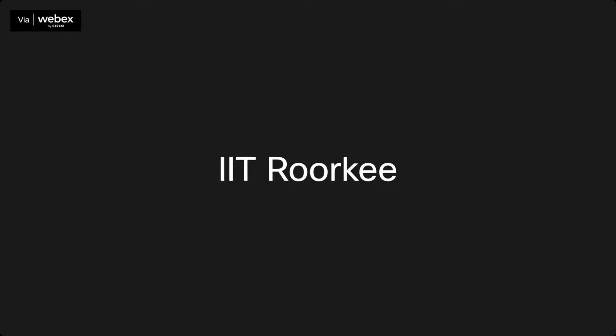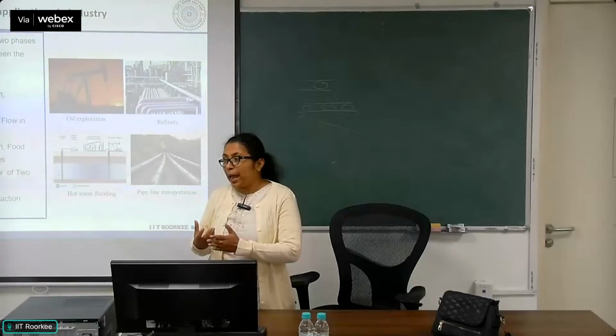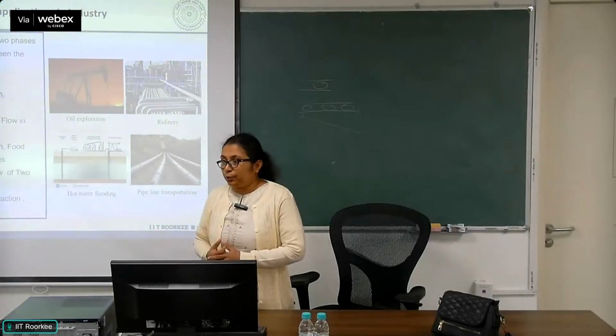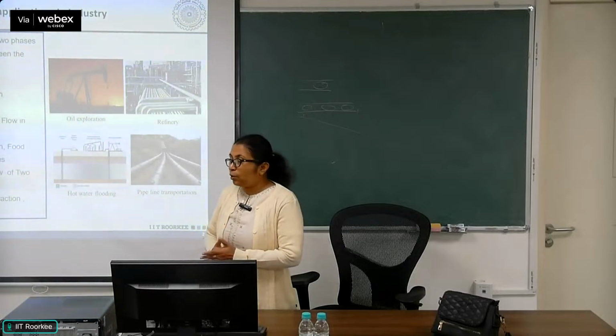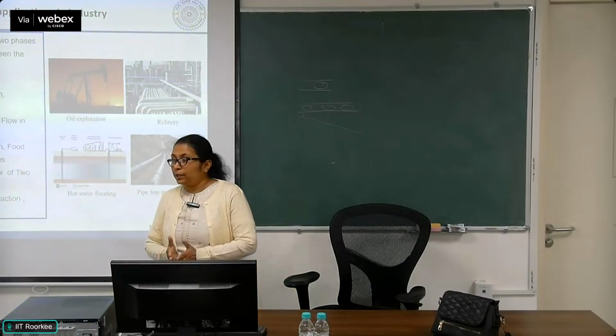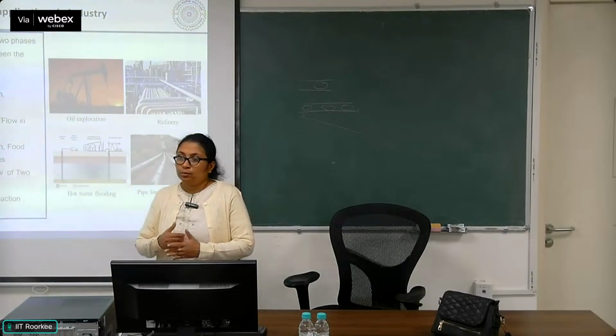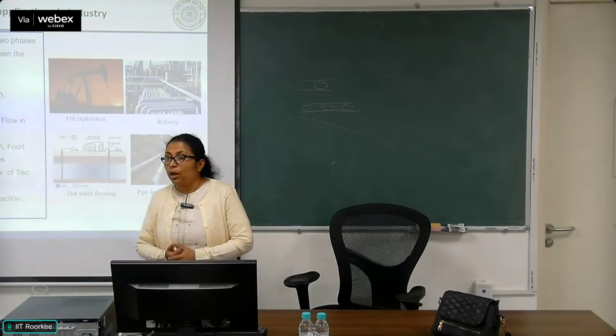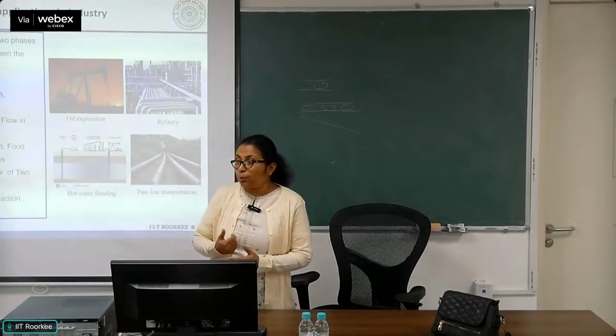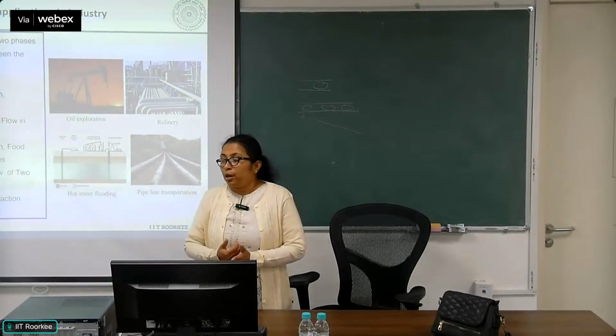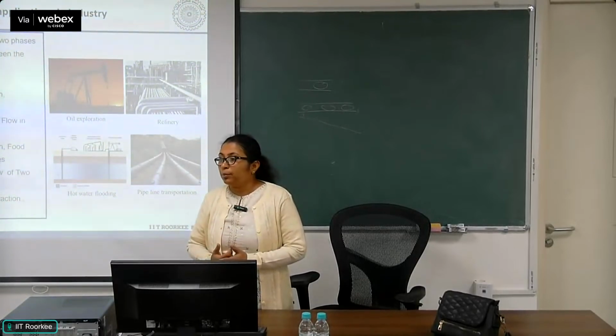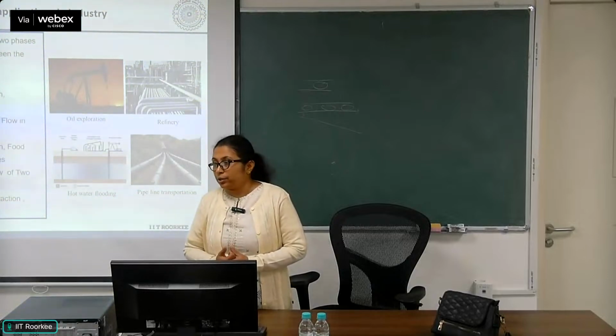What operation can you think of? It is the absorption column, where the sulfur dioxide from the gaseous phase is absorbed in the liquid phase. This is a countercurrent gas-liquid flow, and on top of it you have mass transfer, sometimes also accompanied by reaction.